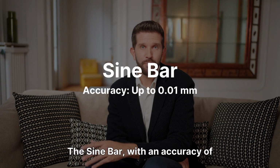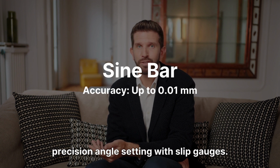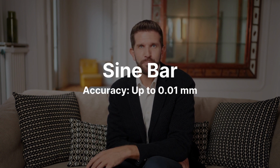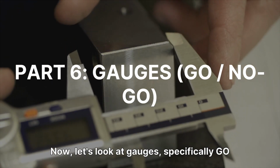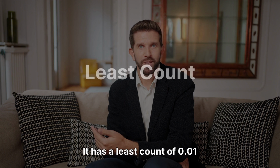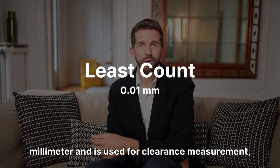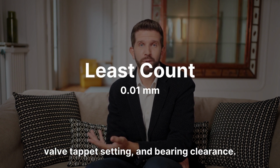The sine bar, with an accuracy of up to 0.01 millimeter, is used for precision angle setting with slip gauges. Now, let's look at gauges, specifically GO/NO-GO gauges. Starting with the feeler gauge. It has a least count of 0.01 millimeter and is used for clearance measurement, valve tappet setting, and bearing clearance.